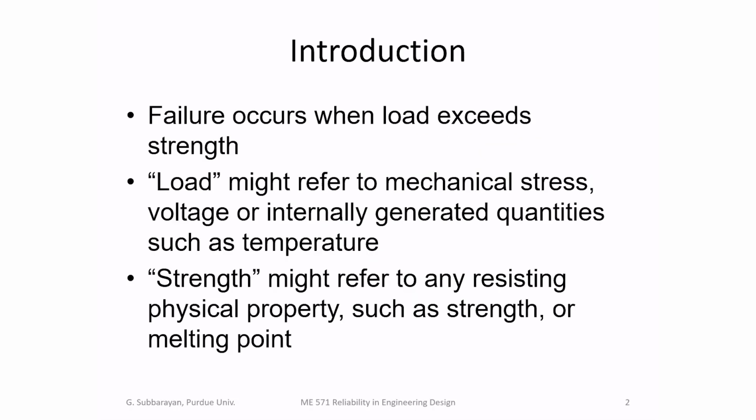So we know that failures occur when load exceeds strength of the material, and in our case we might refer to load as mechanical stress or any quantity that is imposed and that is resisted by some material property that we will call strength.